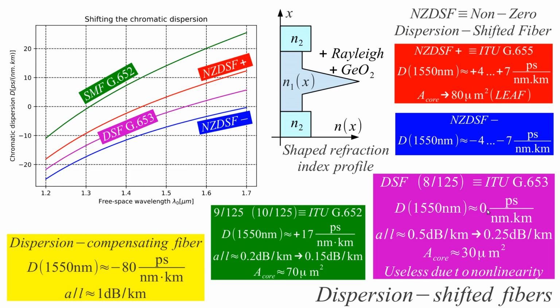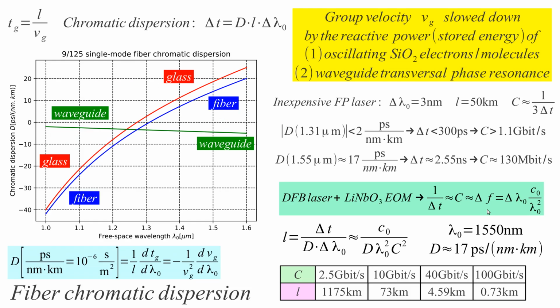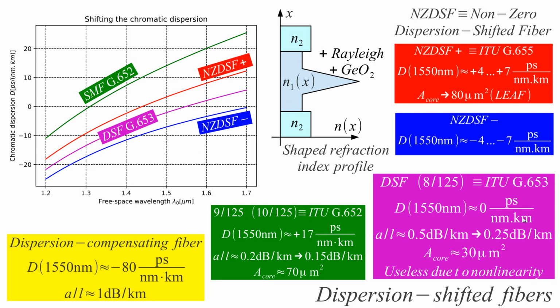The dispersion coefficient is not a problem here, but this can be worked out by linearly processing this signal. If we get into non-linear effects, we can no longer remove intermodulation distortion, and that is a big problem. So, what is the solution today? Either use standard G652 fiber. This is still alive, while this was dead in a few years.